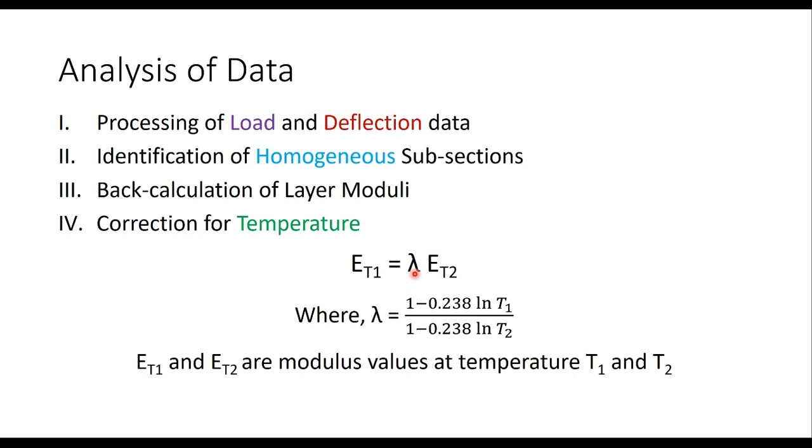ET1 is equal to lambda times ET2. That is the elastic modulus at temperature T1, and the elastic modulus at temperature T2. And lambda is (1 minus 0.238 log of T1) upon (1 minus 0.238 log of T2).